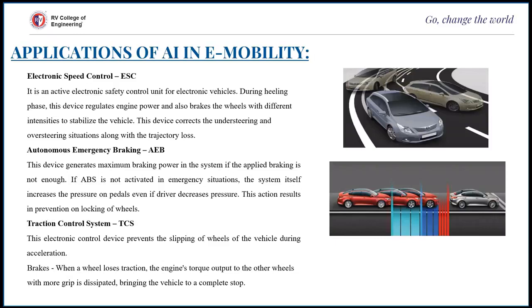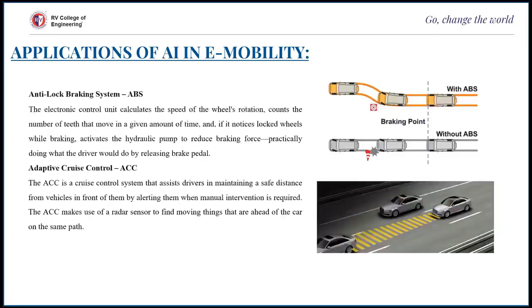To solve this issue, there are many speed sensors which convey the information to the traction unit, where it engages the brakes of the problematic wheel and then permits the power of the engine to be distributed overall. Even in the motor power, when the driving wheels begin to slip, the system engages the brakes on those wheels and reduces the extra torque and frees the wheels to take advantage of the grip of the road. So this was about the traction control system. Let's move on.